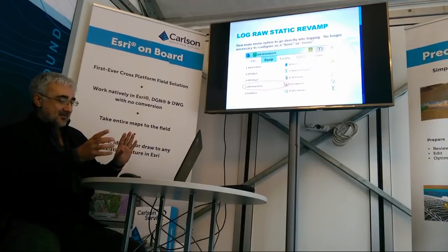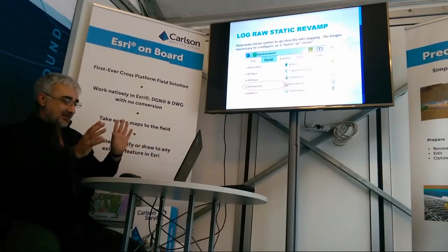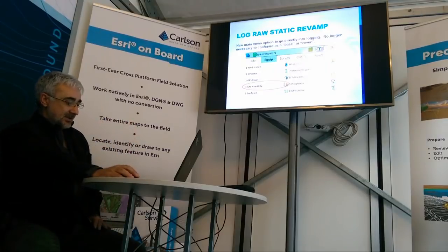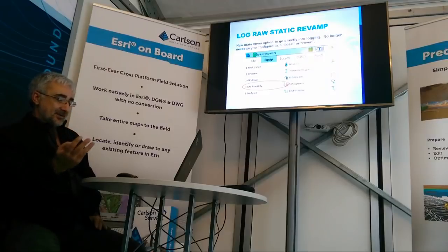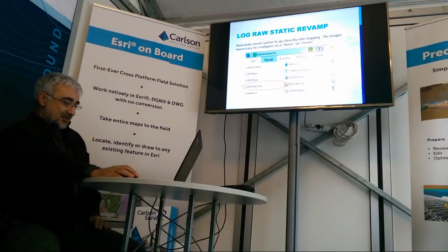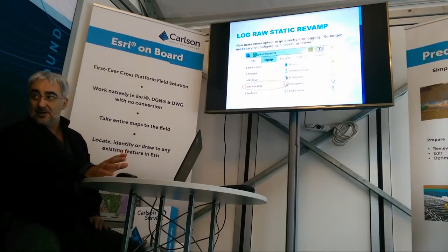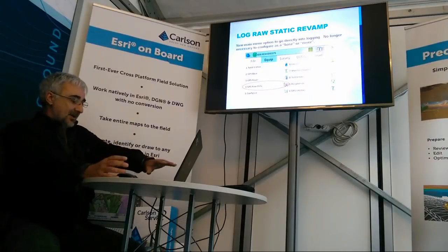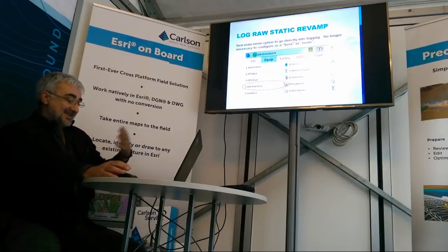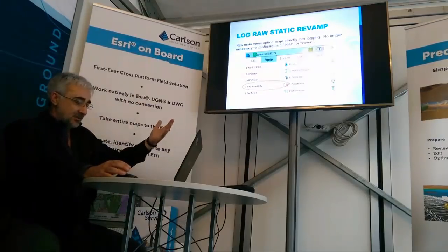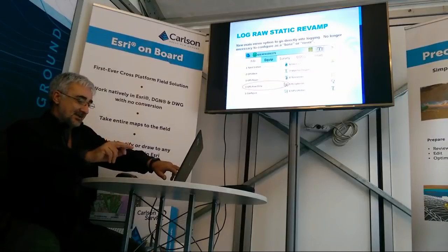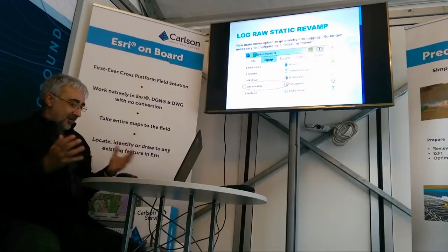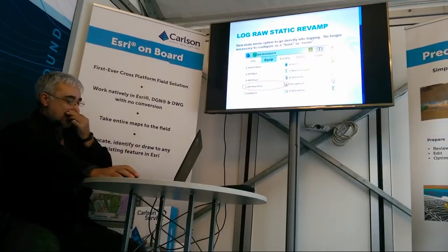You can see in version 6 we changed a few things in the menus. There is a new option here under equipment that is like a third setting for GPS. It's not base, it's not rover, it's raw logging only. For simplicity, you don't need RTK, so everything is together here. Still, if you want to do RTK and logging, you can do rover, and one of the settings is to log raw data, right? But if you only take care of logging, you can get here.